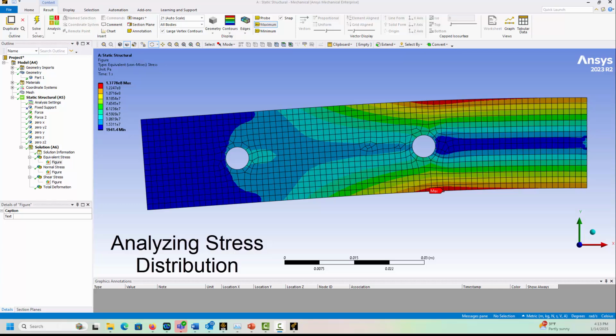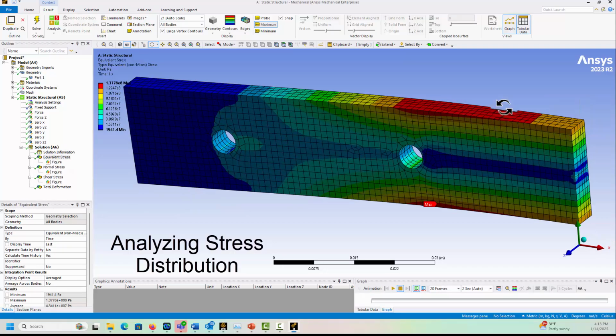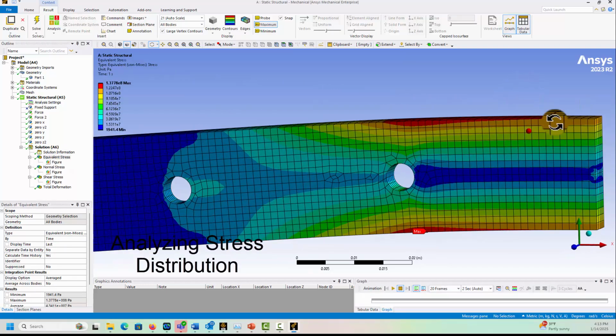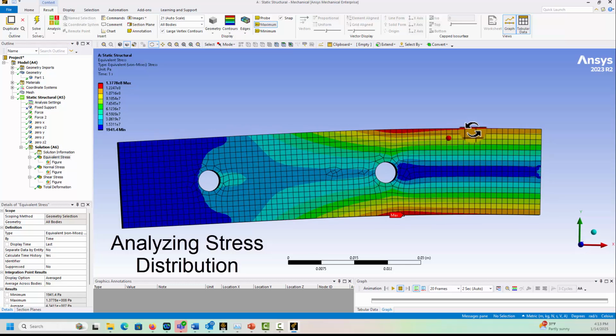Okay, let's talk a little bit about what we're seeing in the stresses. Here I'm looking at my equivalent stresses, which combine some of everything. Again, we're seeing at this center point there's some funny business coming on, but I'm not too worried about it since it's away from my regions of interest. I can see that there's not a peak stress at the boundary conditions, so that's not going to throw me off too much.